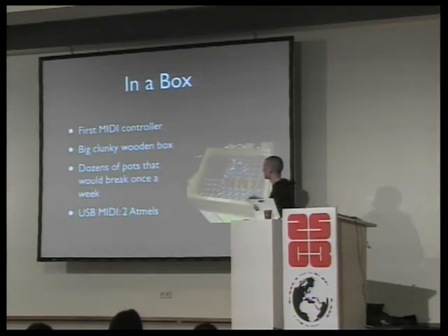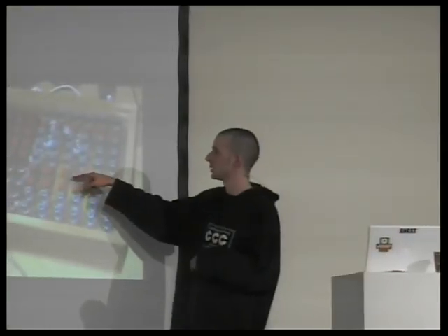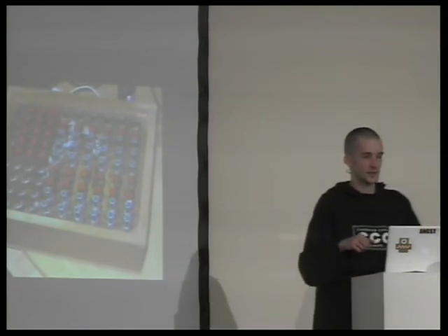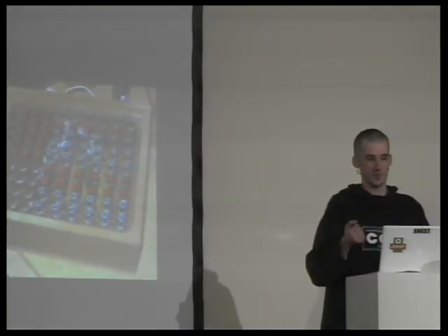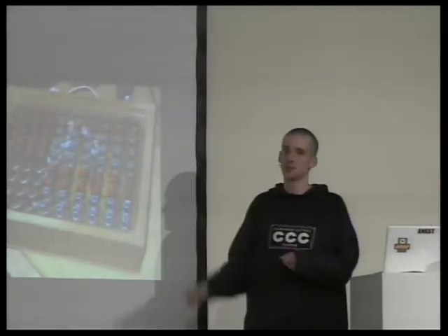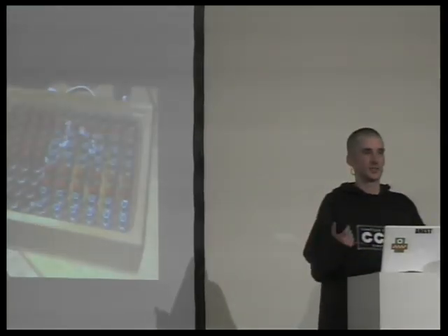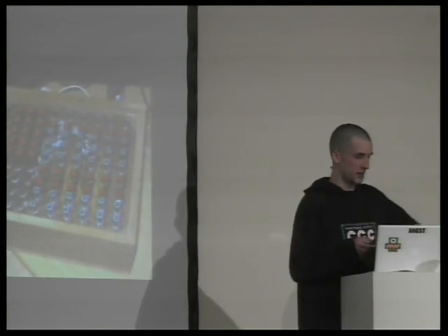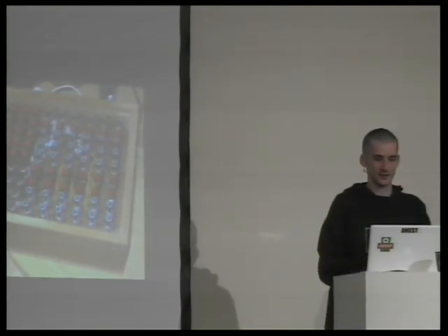And that's what I've been using in this box, for example. There's one controller which polls the whole devices, like asks which value this pot has and whether the button is pressed, and a second Atmel doing USB, which is slightly more complicated, but it's one of the main things which led me on to build all this stuff.